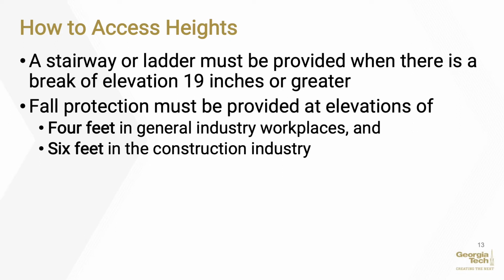A stairway or ladder must be provided when there is a break of elevation 19 inches or greater. Fall protection must be provided at elevations of 4 feet in general industry workplaces and at 6 feet in the construction industry.